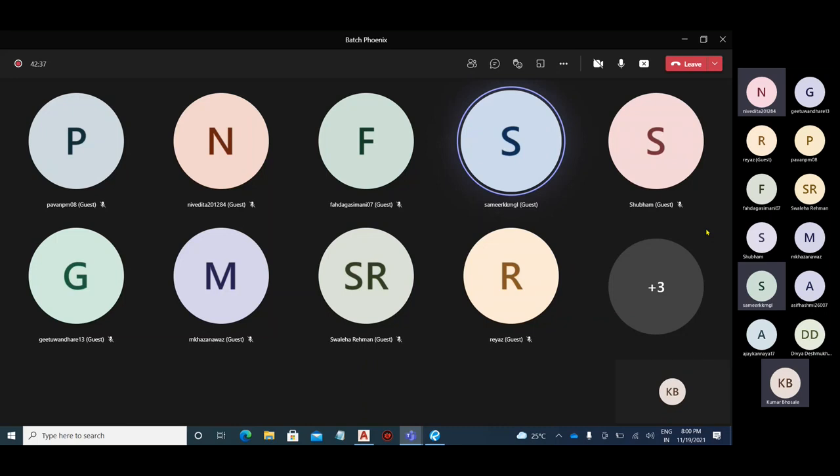Yeah, the scaling part we'll be seeing, how to place the drawings inside this, once we create them. After this, what we are going to see is how to create the drawings, how to create some plans, and after that we'll see how to place the actual plans on the sheets. That is a different part. If the actual drawing is let's say 20 feet long, how to place that into a paper size is a different part of it.